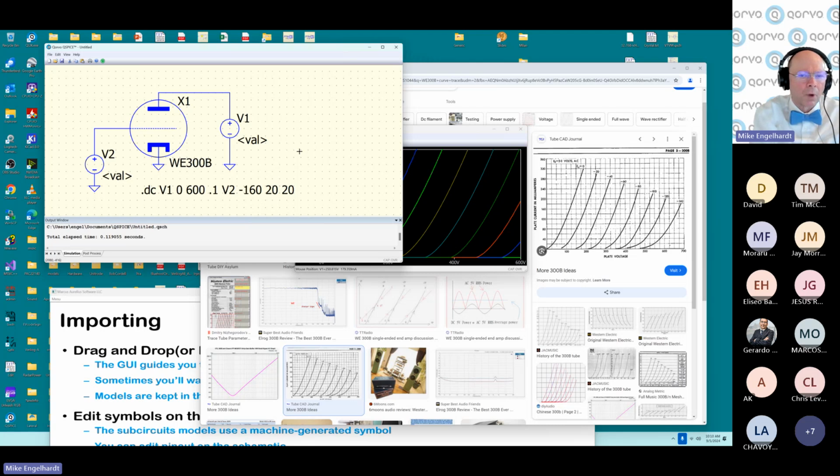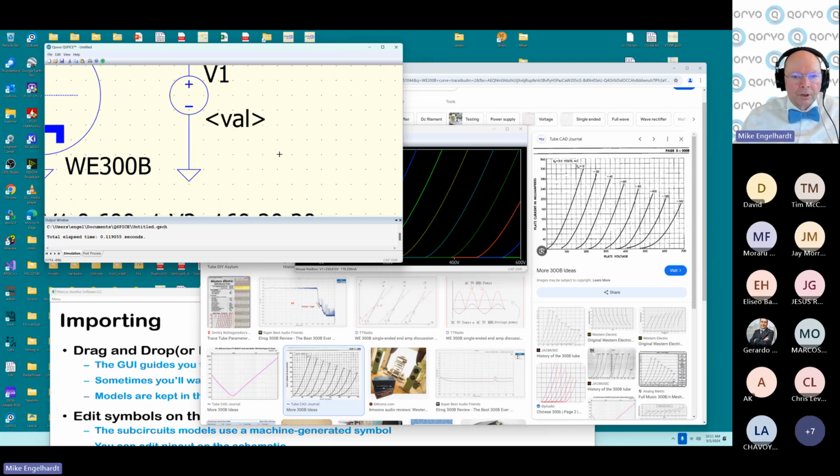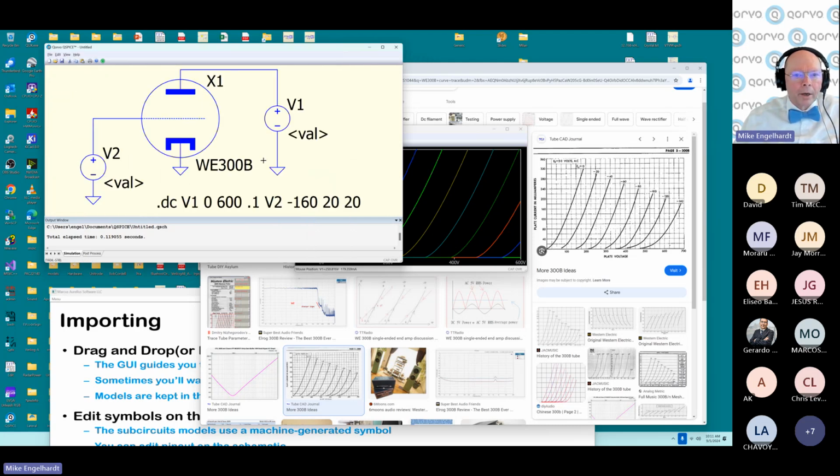I don't use grid lines in the waveform viewer. I don't use scientific notation. If there's anything I can do to remove characters, information, or lit pixels on the screen, it's a benefit. That lets me look at bigger, more complicated systems. So let me turn off the grid. And the wire grid is fixed at 100.